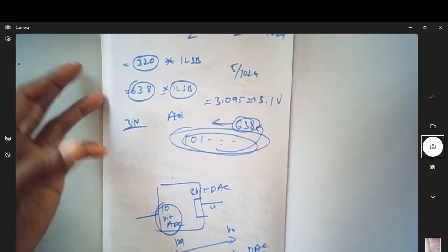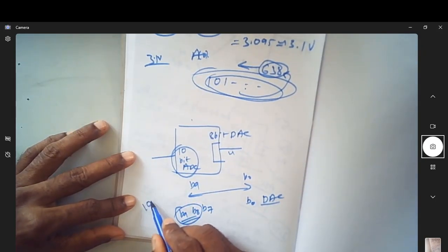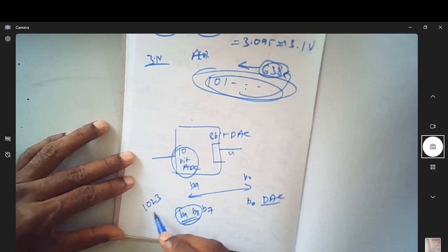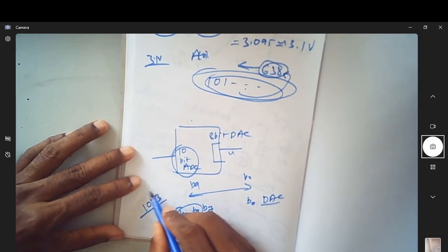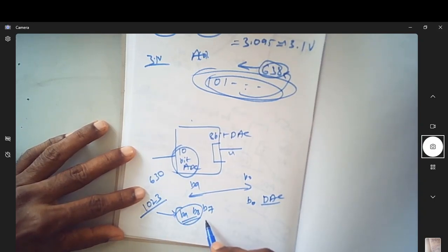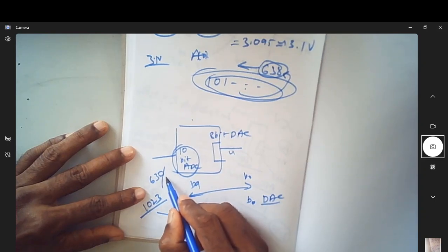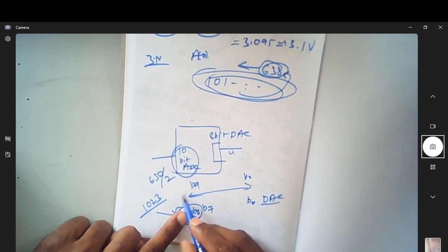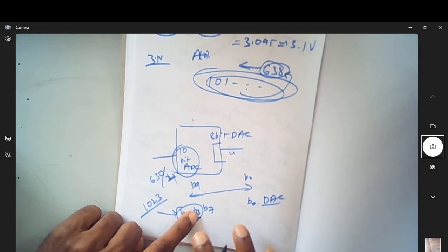So when you don't have these 2 bits, suppose that you are reading 1023. When you are reading 1023, how do you fit it onto hardly 8 bits? Assume that your read is 630. 630 is not going to fit into this 8-bit number. If you divide by 2, this will be made 9-bit. If you divide by 4, this is going to fit into 8 bits.